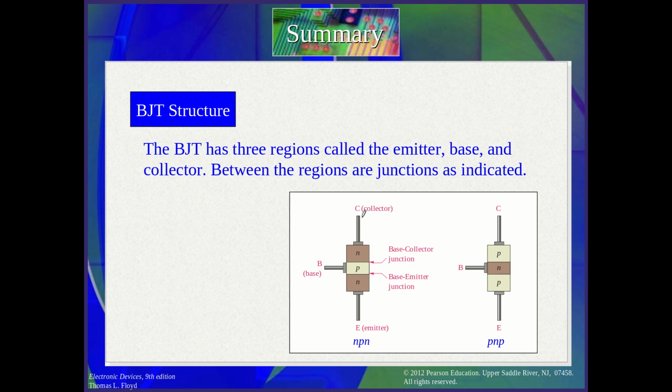So let's say an example. I want to know what is the beta DC for the transistor shown here. So you take any value for the IB and you see the corresponding IC, and then you calculate the beta. Then in the middle here, we take IB. It is 30 microampere, and the corresponding IC is 5 milliampere. Then 5 over 30 micro is 167, which doesn't have any unit because it's a ratio between two currents.